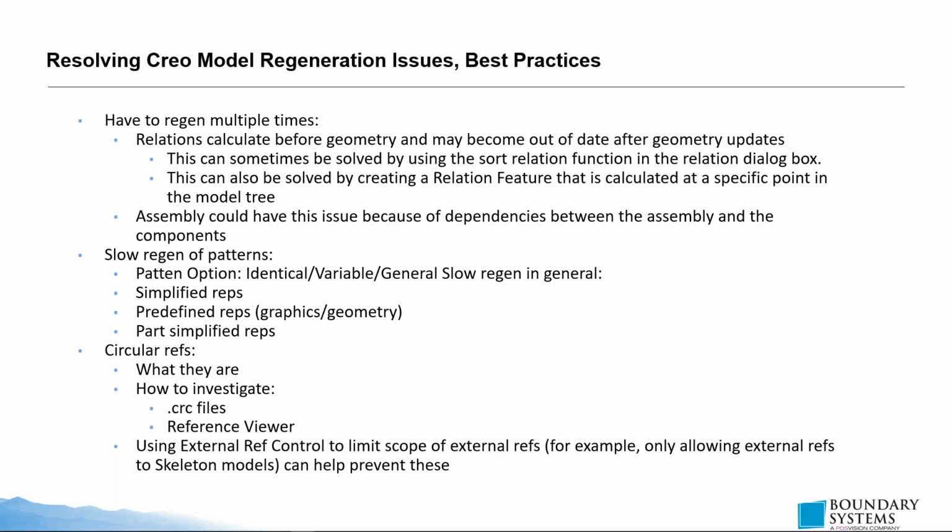And then of course, we also have the ability to use part simplified representations. If we are working inside of an assembly, when you create your simplified reps in the assemblies, one of the things you can do is substitute a fully modeled part with a simplified version of it. So maybe you don't need the holes, or whatever that pattern may be. We can remove that from the simplified rep and still have the overall geometry represented inside of the model.